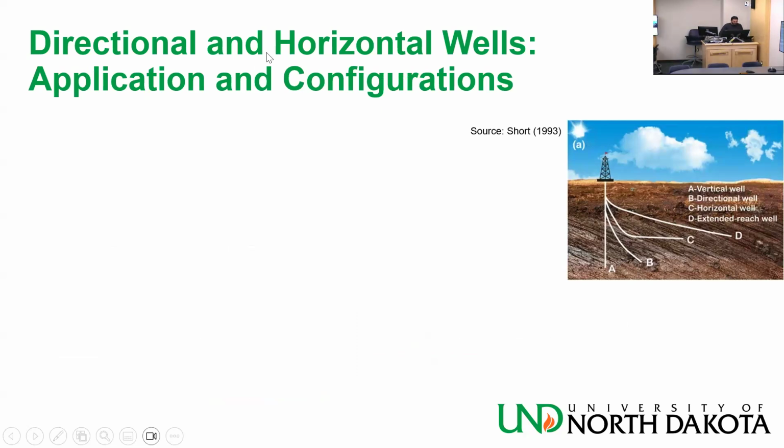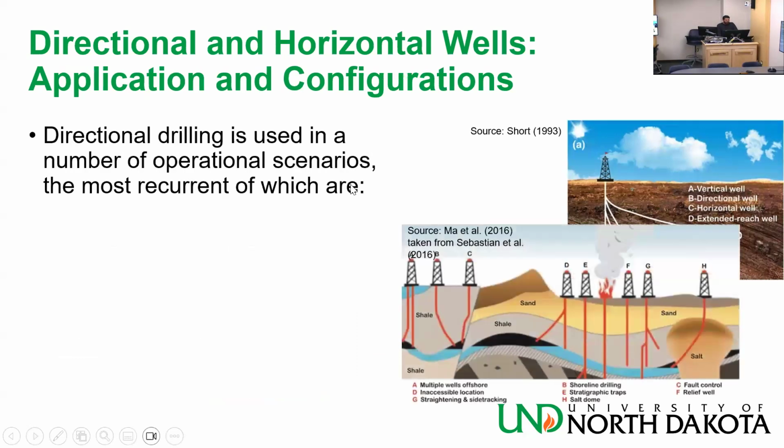Before we get there, let's talk about applications and configurations of directional or horizontal wells. Directional drilling is used in a number of operational scenarios, the most recurrent of which is sidetracking. We had this problem when we got stuck. We had to cut off, cement what we left behind, and then go around it.